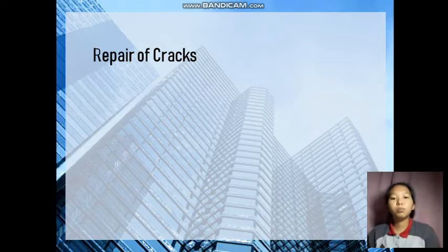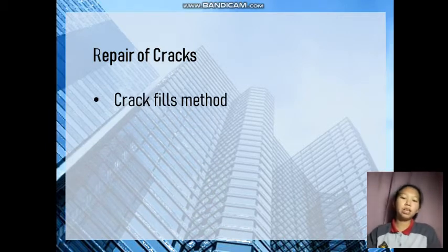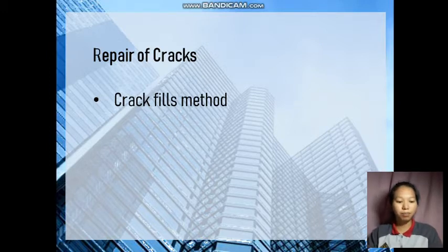Now let's move to repair of cracks naman. So the first method is the crack fill method. This method pours low viscosity resin and ultrafine cement into the cracks in existing concrete members to seal the cracks.